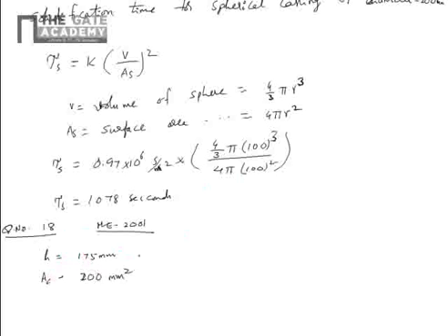The cross sectional area of the horizontal runner is the same, 200 mm square, so you can take any of them. Assuming no losses, indicate the correct choice for the time required to fill the mold cavity of volume 10 power 6 mm cube. Use g as the acceleration due to gravity in meter per second square.